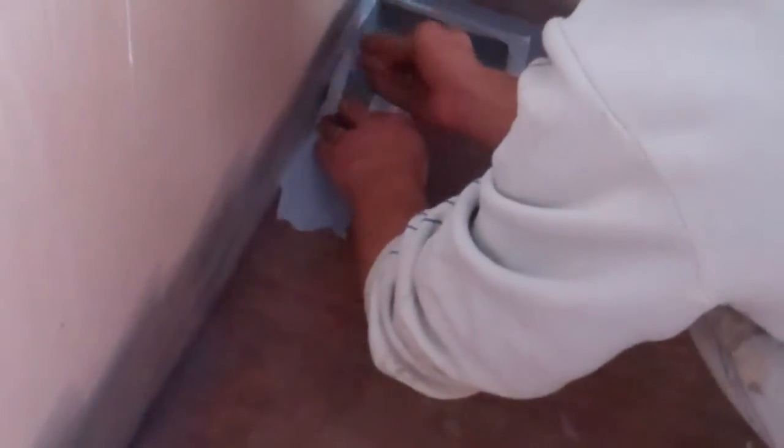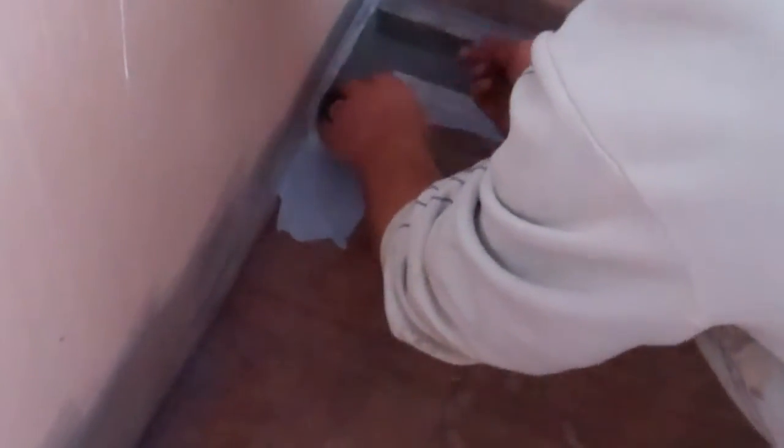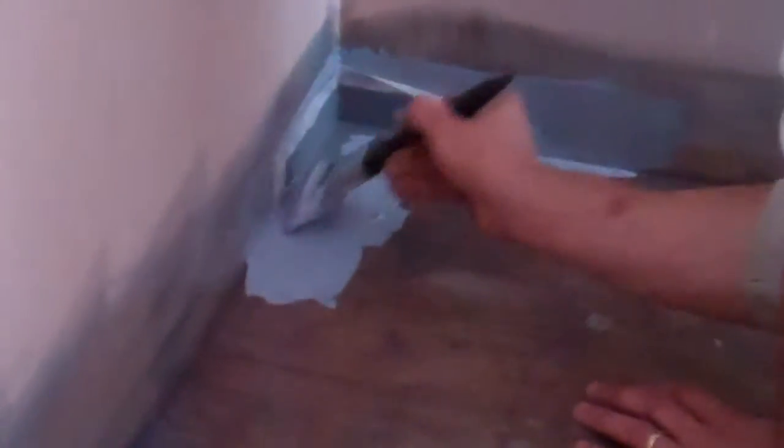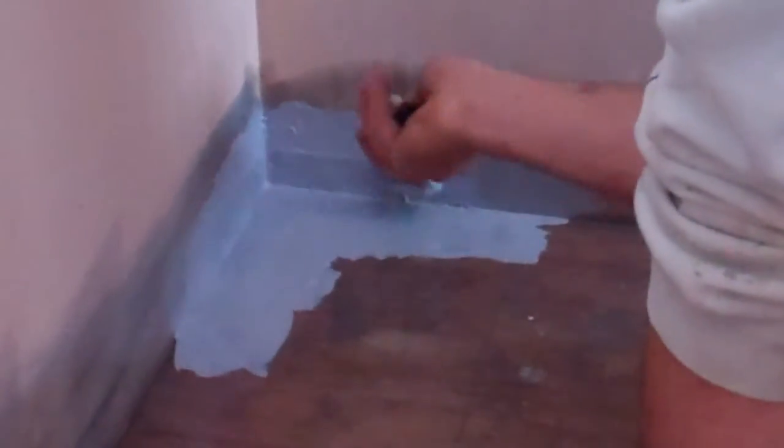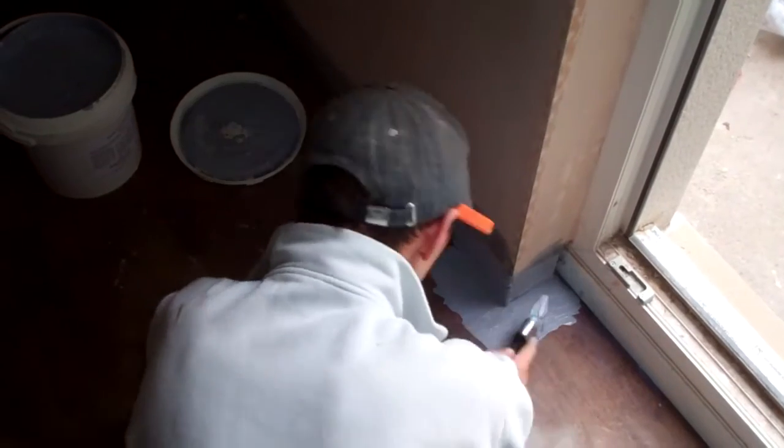We start off by brushing Aquaproof compound into the corner, covering an area slightly larger than the pre-formed corner. We then push the Aquaproof corner into the fresh compound and use the brush to make sure all the fabric borders are laying against the wall and floor before overbrushing with a further coat of the compound. Pre-formed external corners can be applied in the same manner. Corners can also be fabricated on site using the Aquaproof tape.